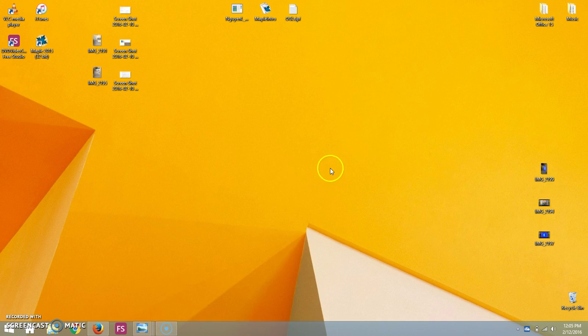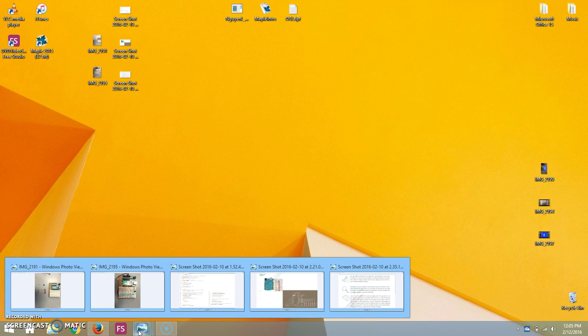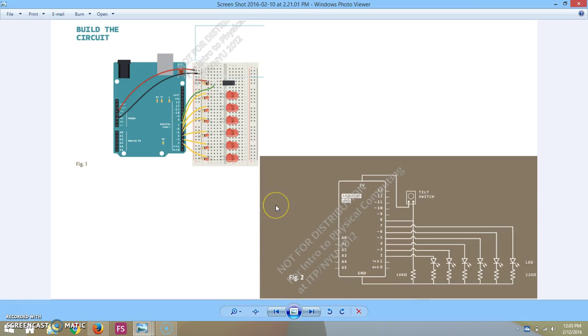Alright, going into the hardware. To start, we have the schematics of the Arduino Chapter 8 project. Here you can see the 5V is going to the switch, and then it's being grounded with a connection to a 10K resistor, and there will also be a wire going from the tilt switch into pin number 8 to collect the input of the tilt.